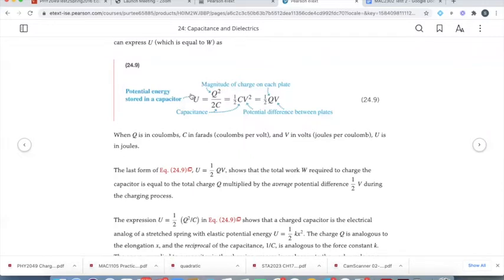If you ever come across one of those old tube TVs that's been sitting around, maybe your grandparents up in the attic have an old tube TV, never ever open it up and play with it. Those old giant tube TVs had huge capacitors in them that can store energy for decades. It still happens every now and again. You'll hear about somebody opening up an old TV that hasn't even been plugged in 15, 20 years and dying because they get shocked to death.